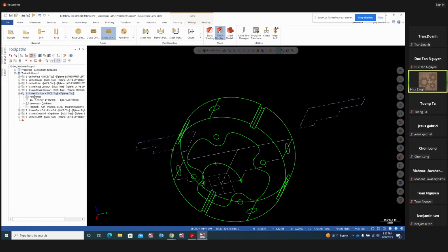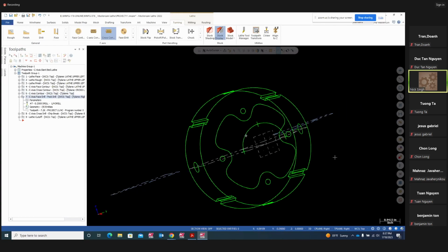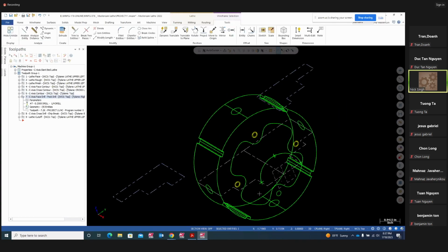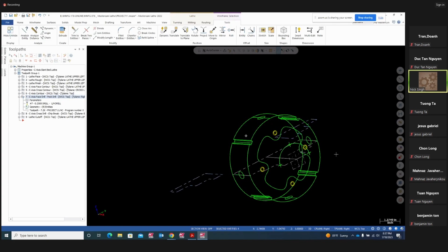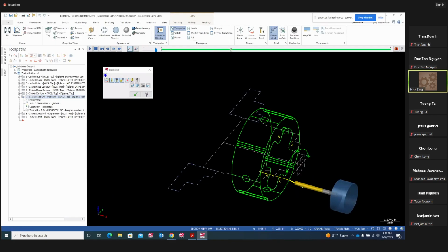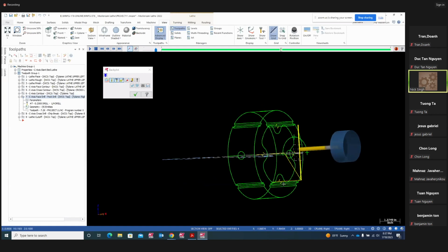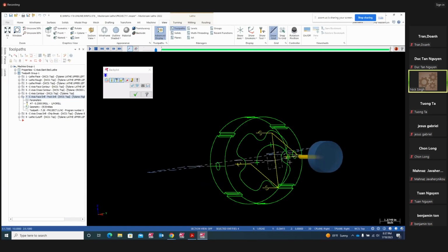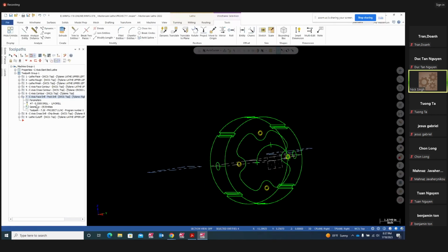Okay, so that is your C-axis contour. Then comes your C-axis face drill. We did that also last week. So these holes 1, 2, 3, 4, these face drill. That's your C-axis face drill. So that tool comes and goes straight in, and make sure it's going to retract enough, and it's going to drill the four holes on the C-axis face drill.